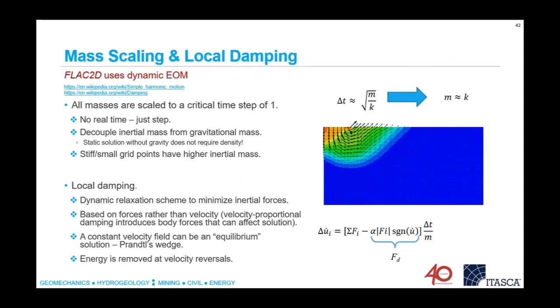But for those of you who dealt with dynamic analysis, you know that typically dynamic problems require a very small time step. If you're dealing with static or quasi-static analysis, having this tiny time step to arrive at the solution will be very impractical. So we actually play games with the time step while solving dynamic equations of motion. And that time step is shown here.